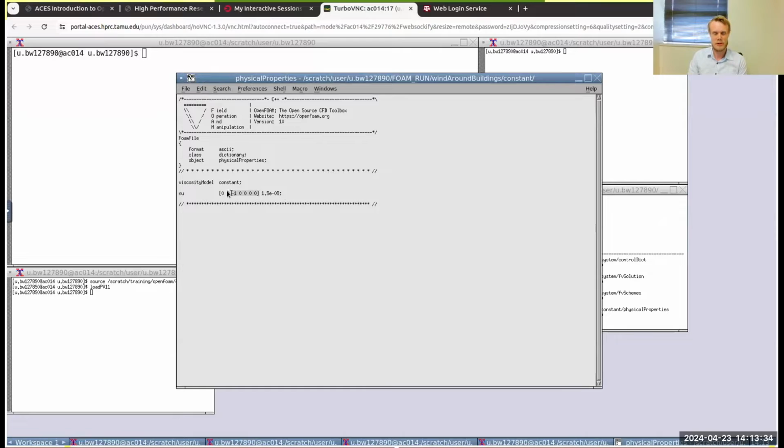These numbers in front of them, I should explain, is OpenFOAM has a way to check that the dimensions of all the variables they use are correct. So this vector is basically a way to dimensionalize a constant, and each one of these elements of the vector represents an SI unit. So we've got length, mass, time, etc. So if you know what the dimension of kinematic viscosity is, you can work out which one is which from this.